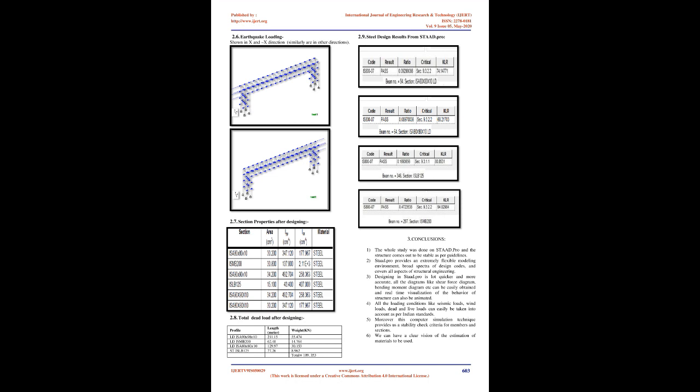As per IS 800:2007 clause no. 2.2.4.1. Unit mass of steel, P equals 7850 kg/m3. Modulus of elasticity, E equals 2.0 x 10^5 N/mm2. 1. Dead loading as per IS 875 part 1. 2. Live loading equals number of persons, 150, times 75 kilograms times 9.81, divided by 30 times 1, equals 3.67 kN/m2, taken as 4.0 kN/m2. 3. Earthquake loading as per IS 1893:2016.